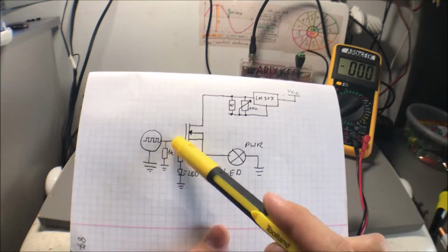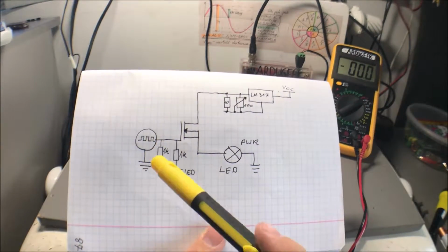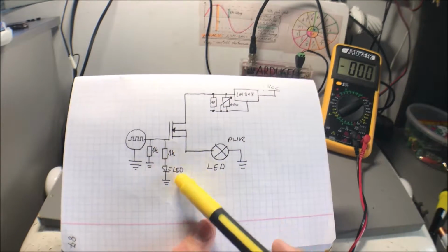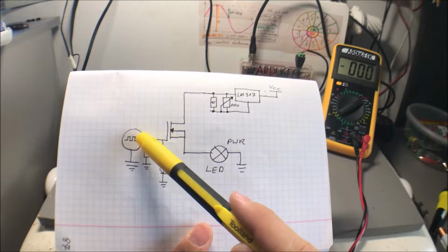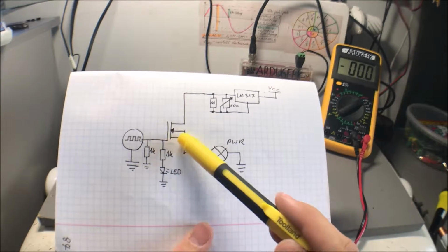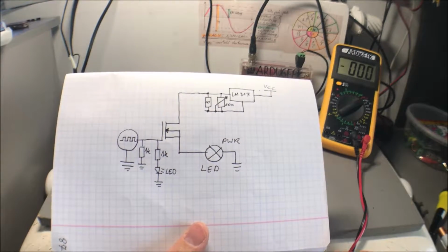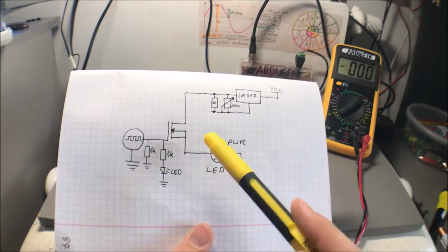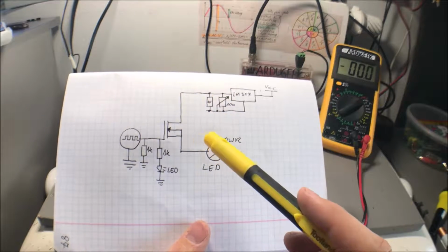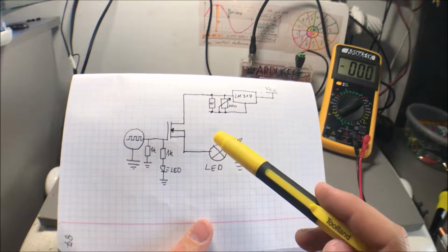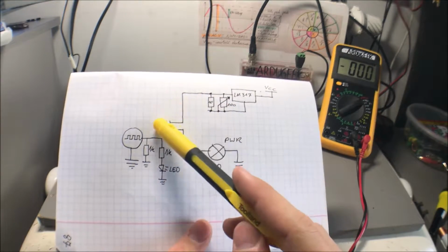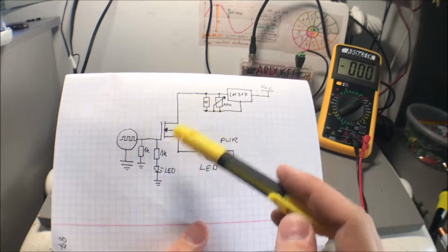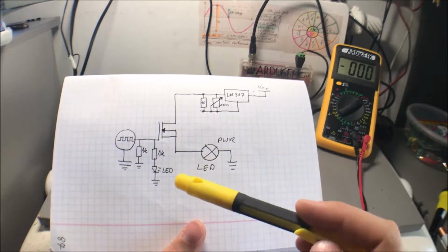Of course, to lower the voltage a bit, we connect a 1 kilo ohm resistor here, and to monitor if we have connected some kind of signal, here we have the LED. So to lower this signal onto the gate, here we have the gate of this transistor. This transistor has a built-in flyback diode from the drain to the source. So that's pretty much it, and when we supply it in here, it switches our LED on and off.